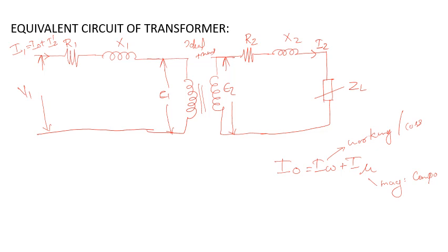Okay. And we have already discussed the phasor diagram of the ideal transformer in detail. So once again I will draw that. Flux phi, due to the supply V1, the same flux will induce E1, and due to the same flux E2 will induce, and both E1 and E2 are 180 degrees out of phase with V1.